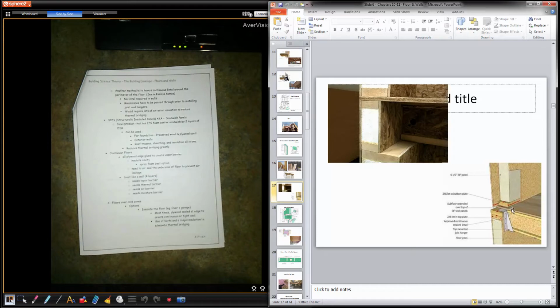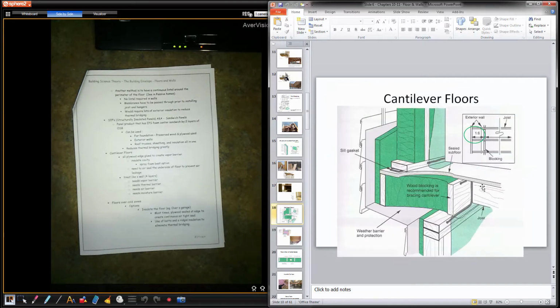So you can see sealing between things is very crucial. Seal between layers. So the floor sheathing gets sealed to the top plate, which gets sealed to the SIP. That 2x6 piece that falls in between gets sealed to the sides of the OSB. So lots of caulking to be put in place prior to dropping down membranes. But it's a system.